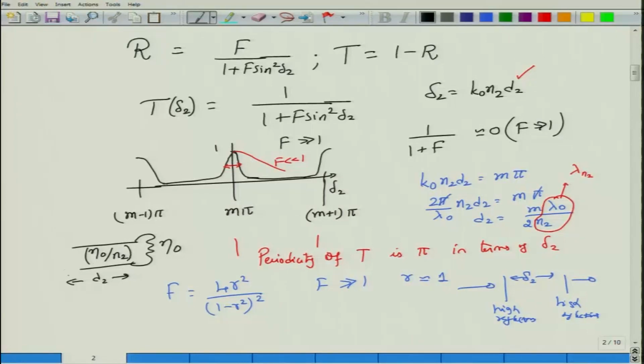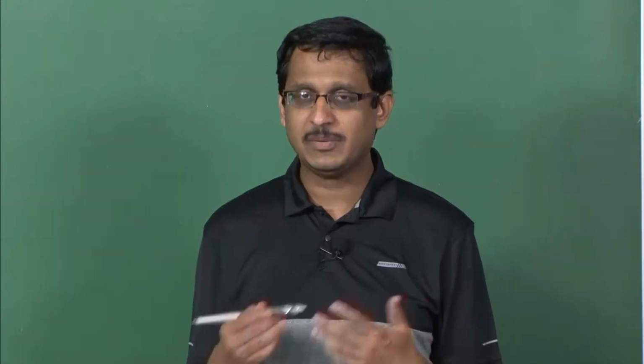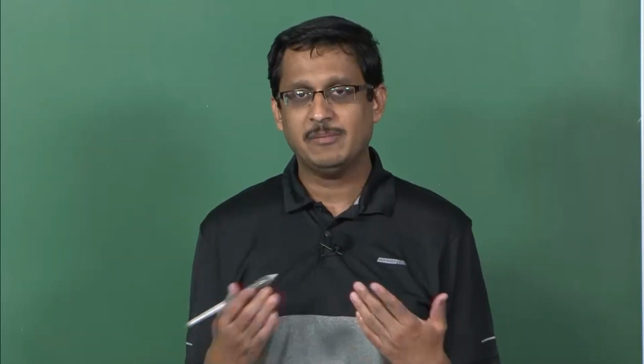Okay. So if you actually look at the overall effective impedance and calculate the corresponding value, then set the required value for d2, calculate the reflection coefficient and then obtain the transmission coefficient, and set the value of d2 such that you achieve this condition, you will end up having the same condition as we have derived from the matrix approach. Okay. But when you go to multiple layers, the matrix approach is easier to program, and therefore that is the approach that we are going to take care of.